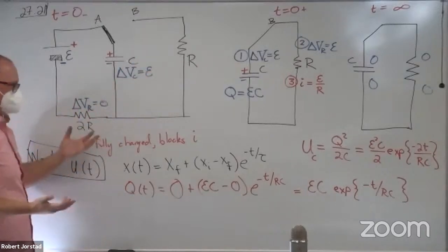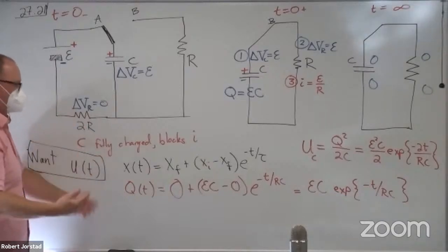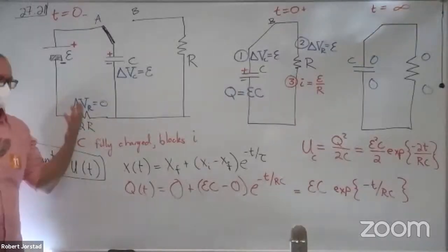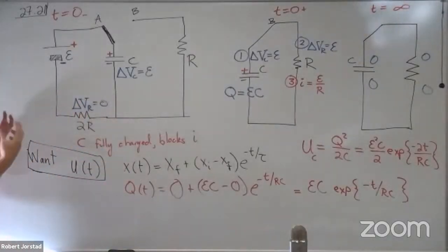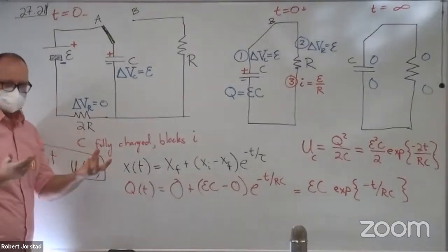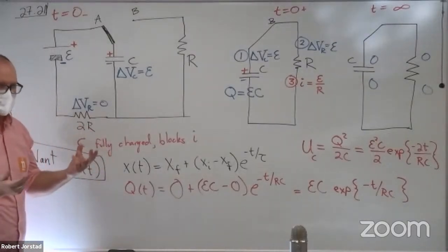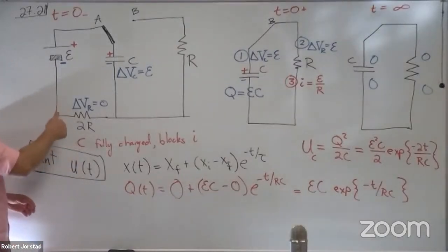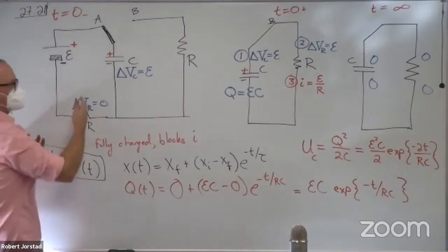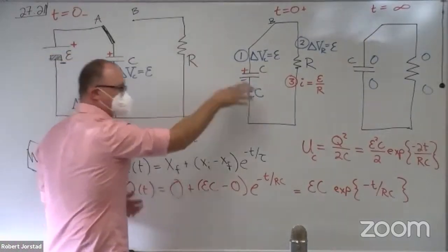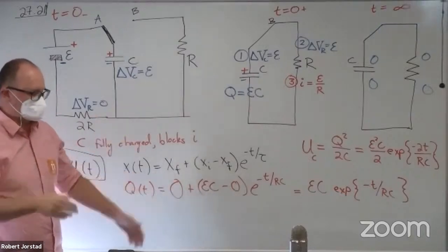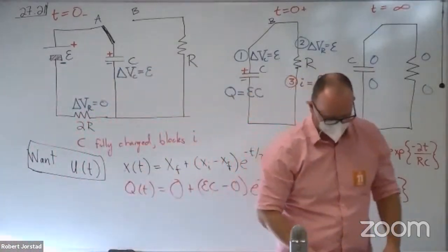So based off that, which time constant is bigger? Charging. So which takes longer? Charging. That's what the time constant's all about. The time constant is kind of like, which thing takes longer? Everybody good with that? That's all I was trying to get at. So the 2R does make a difference when you're charging, but it just didn't happen to matter in this particular problem because we were worried about discharging. So far, so good? Sorry if I made that more confusing than it needed to be.